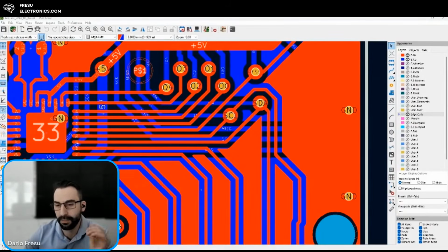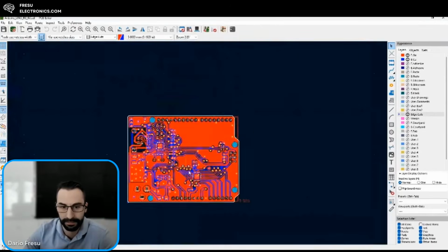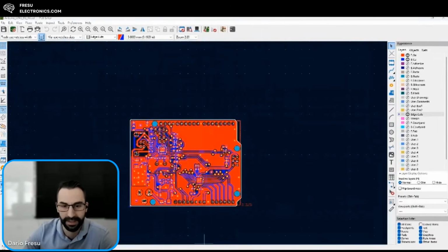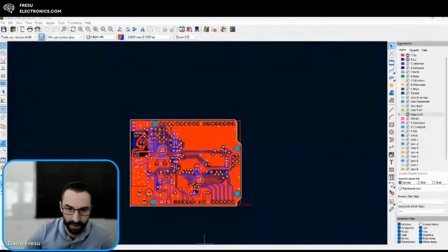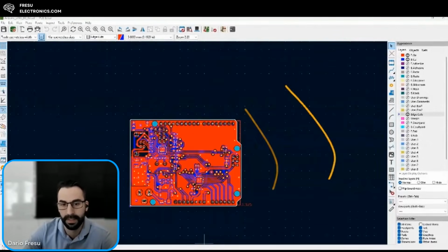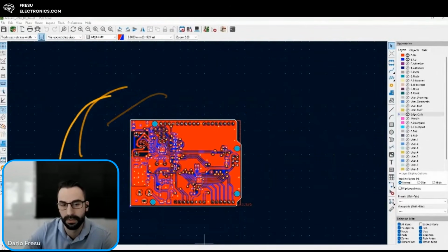Because once I put the antennas to measure what are the fields that this board is radiating, what I'm going to see in here is all the fields that were supposed to stay within the circuit board. So they were supposed to propagate from one point to the other point between the printed circuit boards. Now, all of a sudden, since they are not contained, they're going to spread around, and I'm going to see them all outside of my board, spreading out.